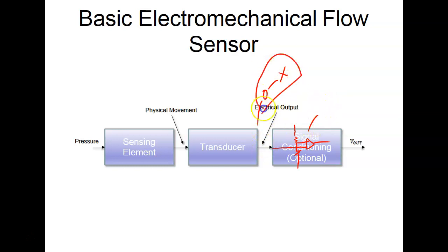If we're going to take the analog output, then we would take it off here. So this pressure sensor that we have gives us both these options. We can get an analog output that gives us a voltage representation of the pressure, or we can have digital outputs which tell us when we exceed a certain pressure, right? That makes sense? Or drop below that.